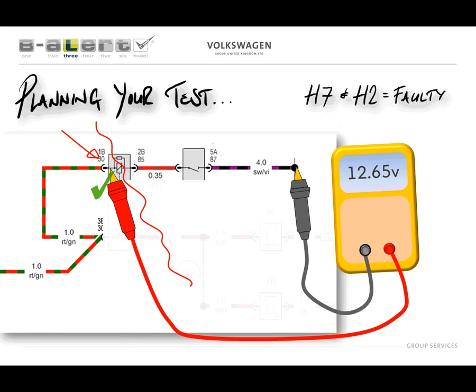The fault is either going to be in the first half or the second half. Whichever half the fault is in, we then split in half again. So in this example, the fault is in the other half. So I test that again, and then again, and just as before with the clunk, in three simple tests, I've split this circuit down to 1/8 of the circuit.